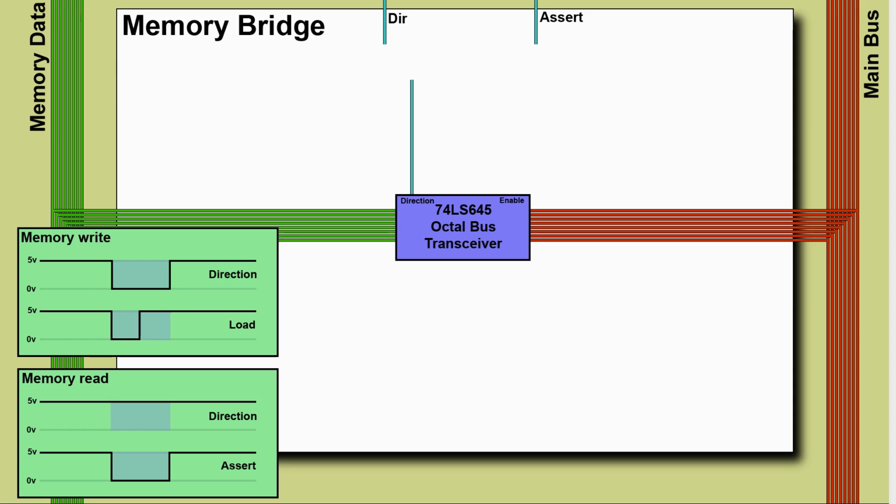So direction line goes where we want, and assert is going to end up being the ANDed together version of these two lines. So if either assert or direction is low, we want to switch the transceiver on and then direction points the way. I'm pretty sure that would work, but I think there is a minor flaw to it. Now this AND gate takes time. Every single other assert is either a 574 or a 541 wired directly to the output from the 3 to 8 line decoder.